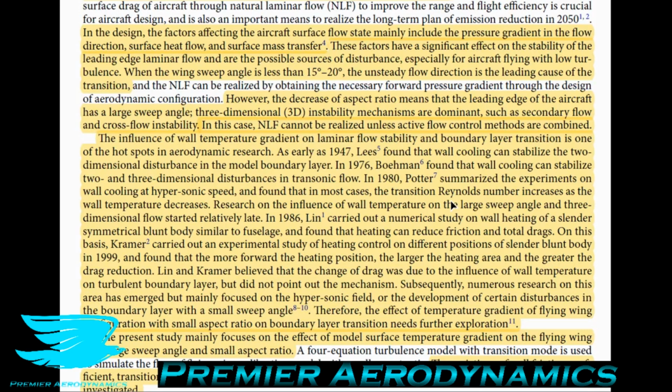What's the difference? So subsonic and supersonic are quite obvious. It's when you go from being slower than the speed of sound to faster than the speed of sound. But hypersonic speeds, that's when you go so fast that the gas you're in, in terms of the Earth, our atmosphere, air, starts to change its composition effectively, where you start to strip electrons off of the atoms and make them plasma. And that happens when you go so fast that there's a lot of heating going on. So that's the general distinction between supersonic and hypersonic flows.